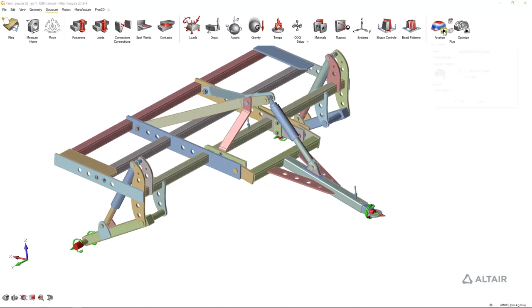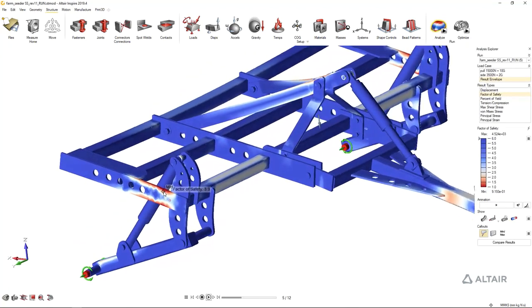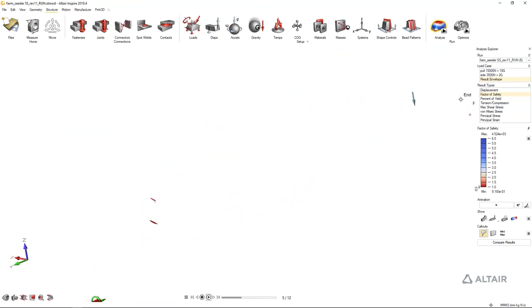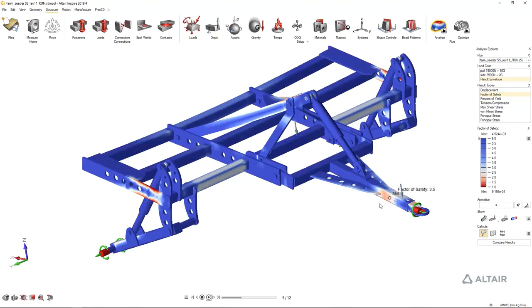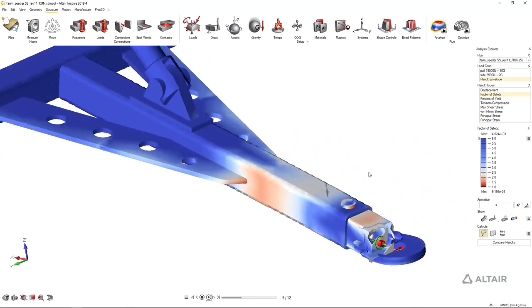And then rerun analysis. You can simply right-click. There's an option that says Analysis Quick Run, or you can just push F8 on your keyboard and Inspire is going to automatically rerun this new design iteration using SimSolid. It takes about 10-15 seconds here and you have the new results already available. So here I've taken about a couple of minutes to get the performance of the baseline structure, quickly modify my geometry, and then look at how my performance has improved, right?